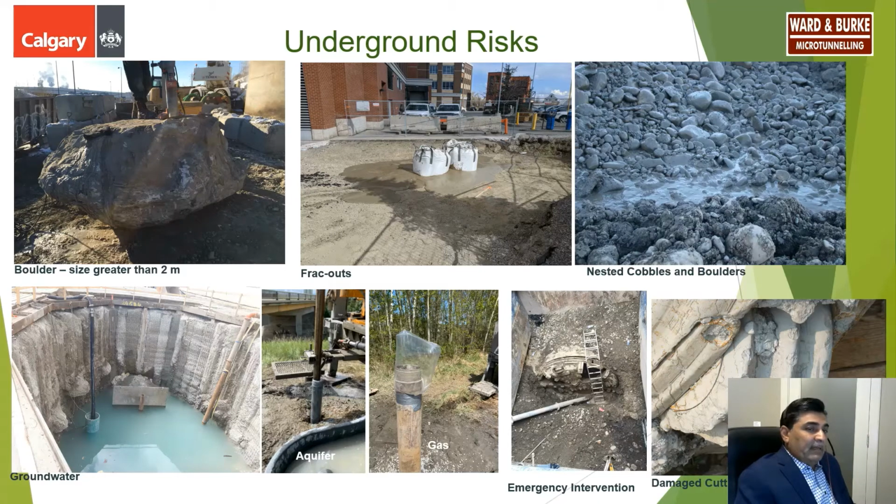So when we say underground risks, we have provided a few examples of underground risks that we encountered on this project and some other projects as well. So boulders, that is a big risk. If you don't specify them properly, then that is a change in ground condition. And you can see here we encountered a boulder which was greater than 2 meters in size, and that was a claim that we had to pay.